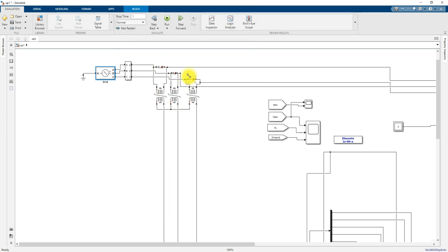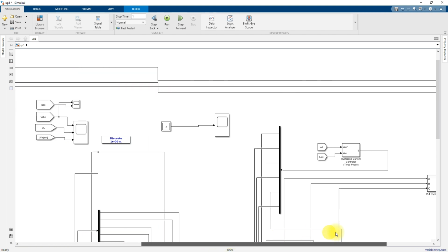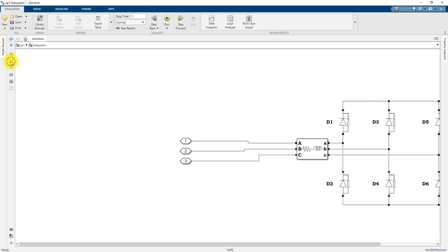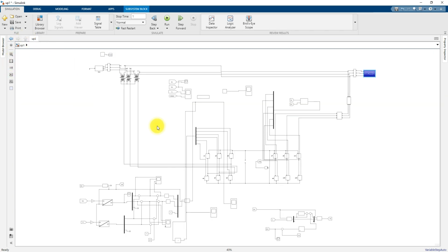and this is known as series. That means the injecting transformer is connected in series in the line, and here we have a non-linear load. So this non-linear load will create the harmonic in the source current. Here we are creating sag, swell and harmonic in the source voltage, and then by means of the nonlinear load it is going to create the harmonic in the source current. So this is going to be controlled by means of the series active power filter and shunt active power filter of the UPQC.